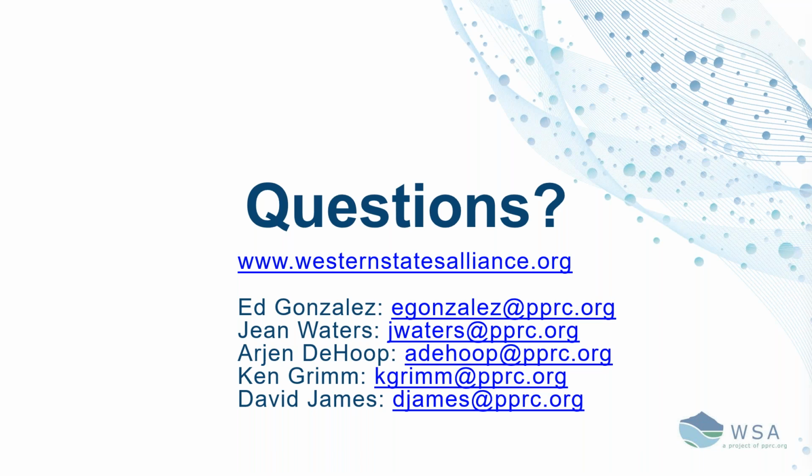Yeah, I can jump in there, Gene. If you have a pretreatment program, you obviously should have a pretty solid background and understanding of what you have in your service area as far as industries and businesses, and they can all be evaluated on an individual basis. Right now, I have a military installation that I've been sampling for PFAS. I'm sampling the treatment plant. I'm also going to move upstream into some more residential areas that have some commercial influencers, an educational institution, and a timber affiliated industry. So, knowing what you have in your system and what geographical area they lie within, do some field sampling, get a geographical idea of where your PFAS may be coming from, and then keep moving upstream as you go along. That's kind of our approach right now.